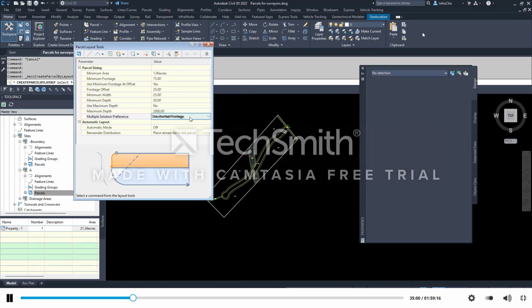Maximum, let's see, use the shortest footage or the smallest area. Automatic could be on, but I'm going to leave it off. Place the remainder in the last parcel, redistribute the remainder, or create a parcel. I'm going to place the remainder in the last parcel if there's excess left over. So we got that set up.